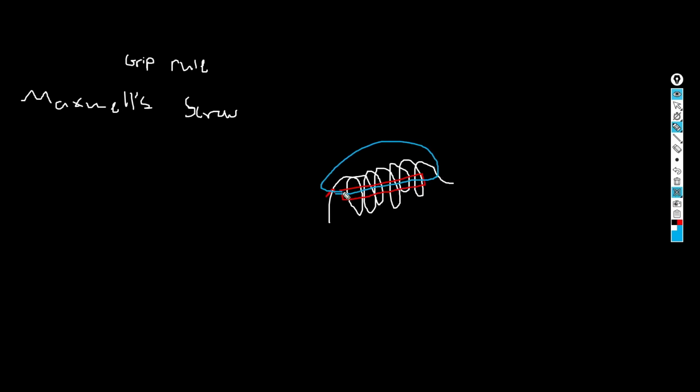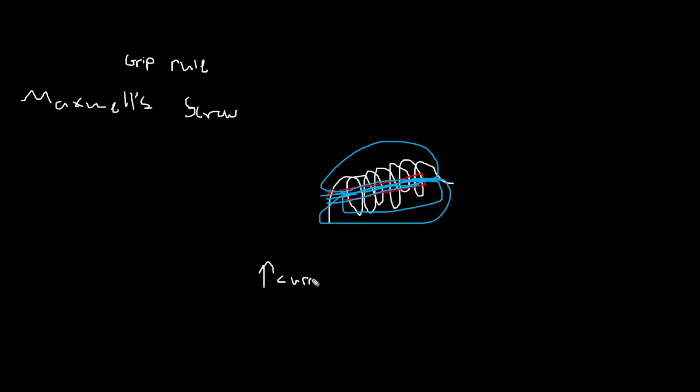We'd have a very strong magnetic field inside the solenoid itself, and here we would have a strong magnetic field, and we can vary the strength of it. So it's more useful than a normal magnet. We can vary the strength by increasing the current, or increasing the number of loops.